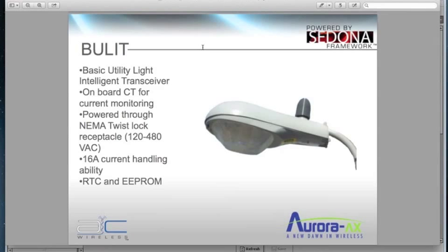And consider 100 parking lot lights, each with 1,000-watt bulbs, all coming on at one time is 100,000 watts of inrush. Well, with control logic, obviously being able to bring the lights on in groups of 5 or 10 and providing offsets to give you the ability to not turn the lights on when a standard photocell or time clock would, by getting a 10-minute offset in the morning and 10-minute offset in the evening, just simply reduces energy.